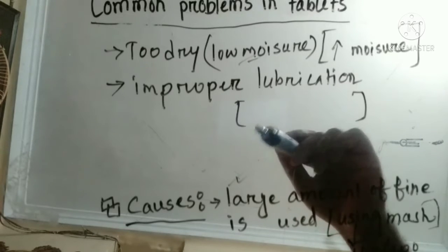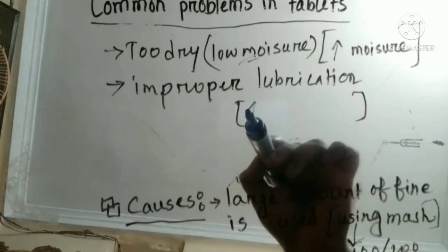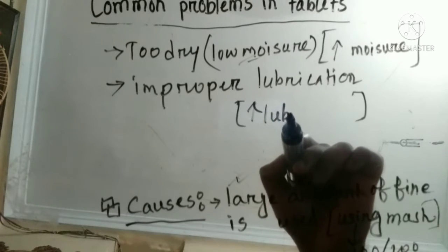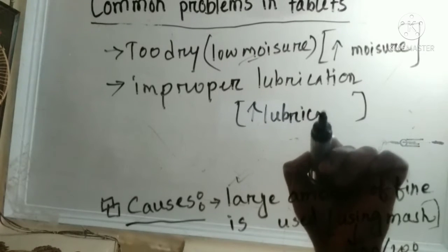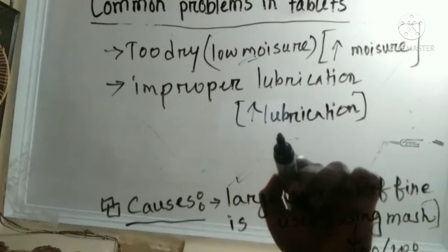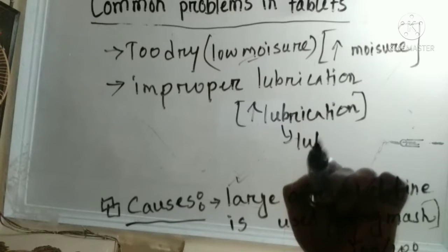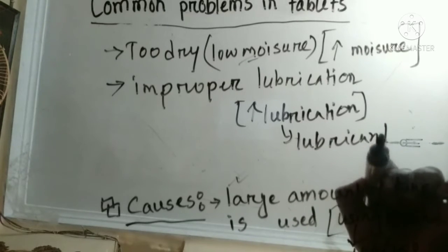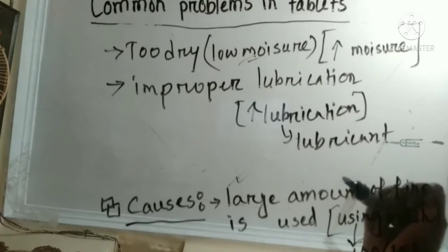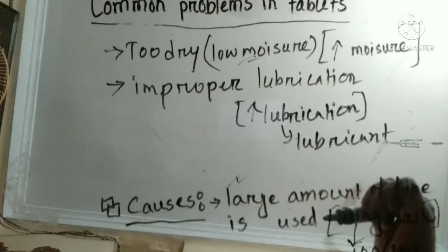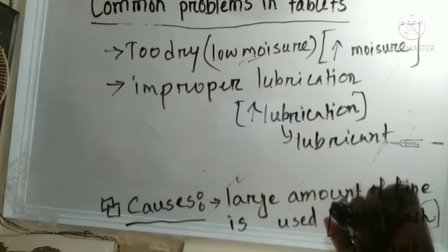In case of improper lubrication, lubrication should be increased by using a proper lubricant. So this is our first common problem in tablets, capping.